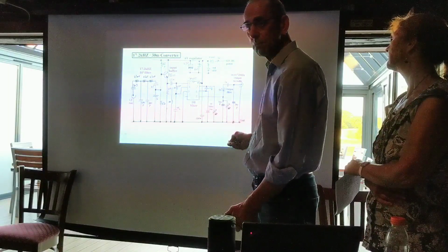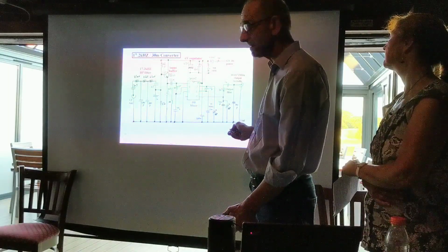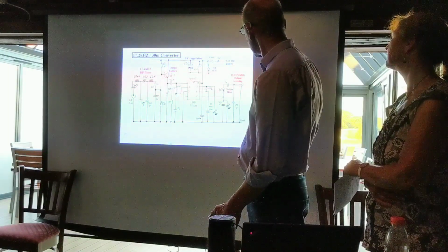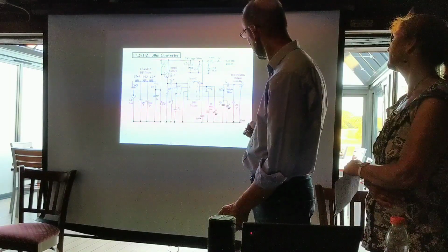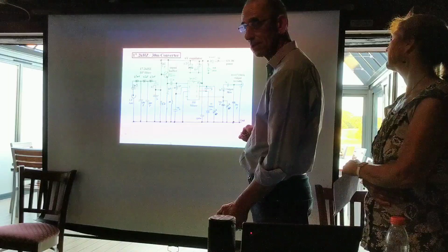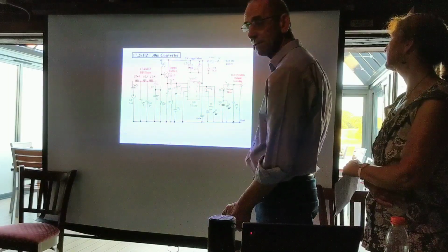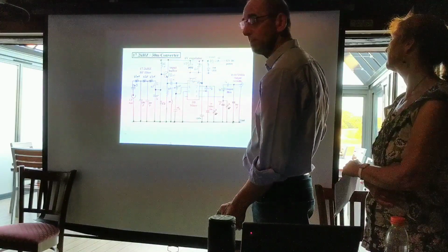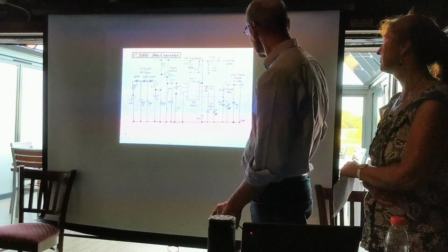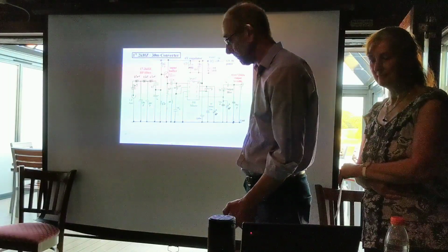This is one of those double balanced mixers, Gilbert cell ones, all made on silicon. And then here's the 10 megahertz local oscillator, which has its own oscillator circuitry built into it. And oh look, there's one of those series tuned circuits, because 10 megahertz is awfully close to 10.0172, so you want to get rid of the 10 megahertz local oscillator that might be present on the output.